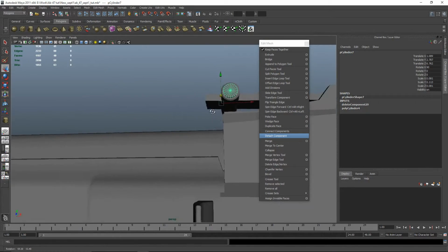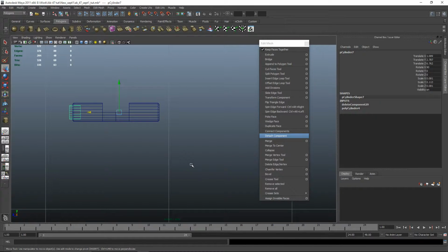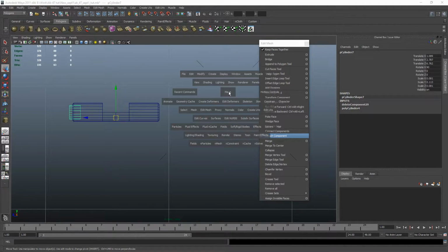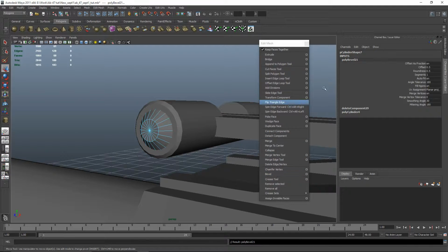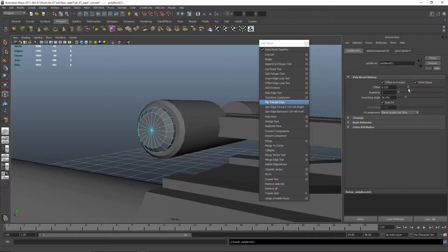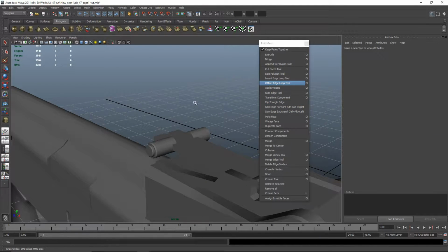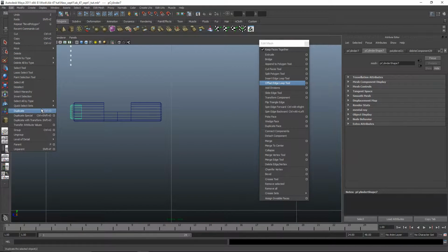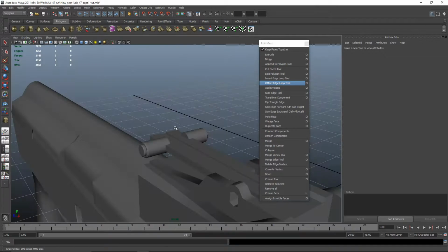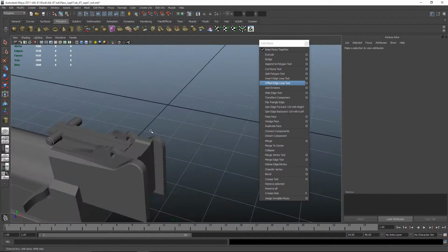Doesn't look right, correct. Okay, so I'll have to insert again. There we go. But another thing I want to do is just bevel this part as well. Something like that. There we go. And now duplicate special. Here we are. That's the side nearly done.